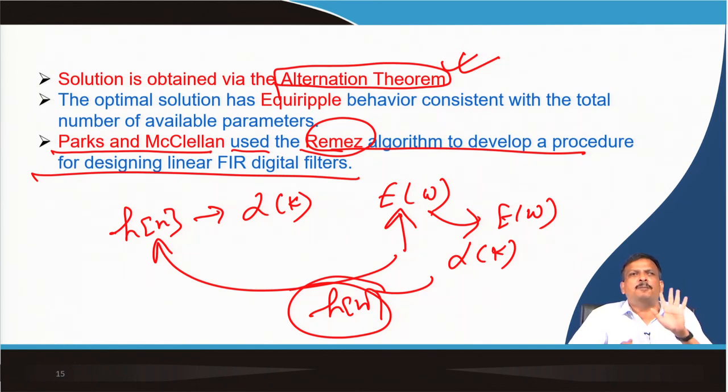So, if I summarize the FIR filter, you have to know the FIR filter, the finite impulse response filter, its properties: it may be linear phase, symmetric or antisymmetric, and the order of the filter may be even or odd. For the linear phase requirement, we know what kind of frequency response will be there. That is common for all kinds of design. Then I go for the design by 3 methods. One is the window method. I can design an FIR filter using window methods: I calculate h of n, multiply by w n and then convolve with the input signal, and I get the desired output.